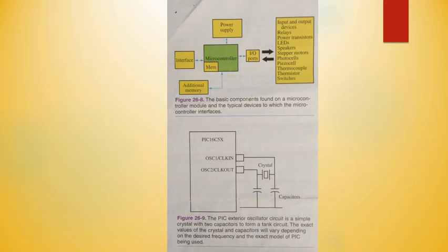Additional components, such as digital to analog and analog to digital converters, can be used to change the digital pulses into analog signals. If you need to drive a device requiring a higher output current, you can simply incorporate a small mechanical or solid-state relay between the output pin and the load device.